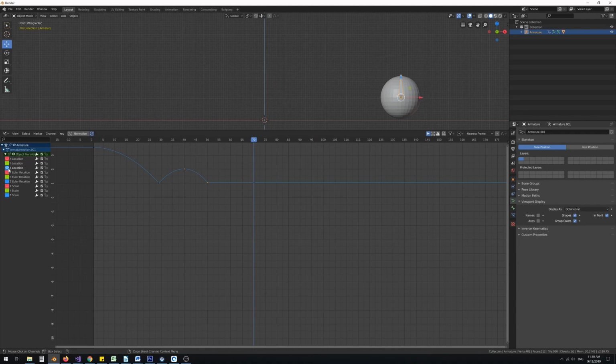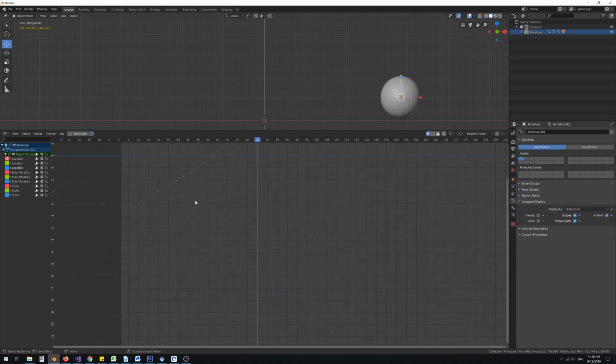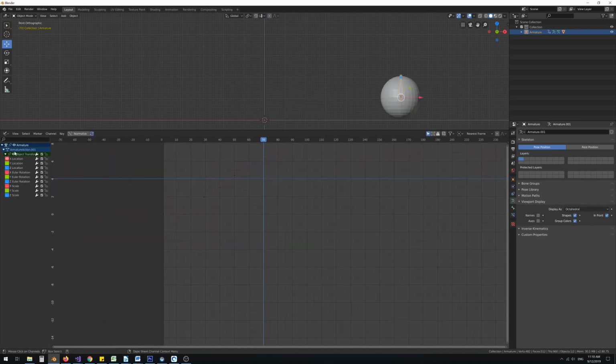So what we need to do is turn off the Z location and look at the X location. And again, in the X location, we're seeing that random amounts of acceleration and deceleration happen, when in fact what we actually wanted is to stay constant. So what I'm going to do is delete these keyframes here. Oops, choose that again, delete keyframes. And I'm going to select the 2 remaining keyframes. I'm going to right click and I'm going to choose linear, because in linear mode, this means that there is no acceleration or deceleration of the ball.